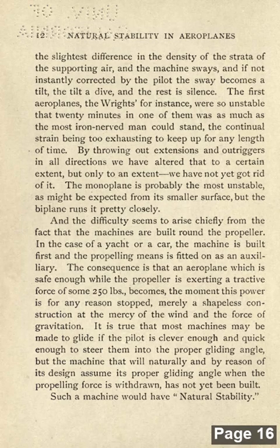The consequence is that an airplane, which is safe enough while the propeller is exerting a tractive force of some 250 lbs, becomes, the moment this power is for any reason stopped, merely a shapeless construction at the mercy of the wind and the force of gravitation. It is true that most machines may be made to glide if the pilot is clever enough and quick enough to steer them into the proper gliding angle. But the machine that will naturally and by reason of its design assume its proper gliding angle when the propelling force is withdrawn has not yet been built. Such a machine would have natural stability.